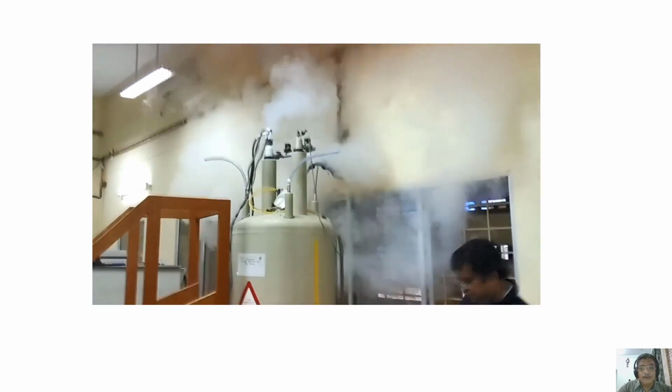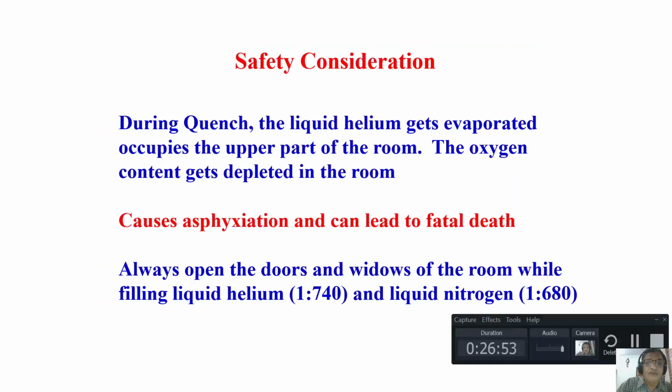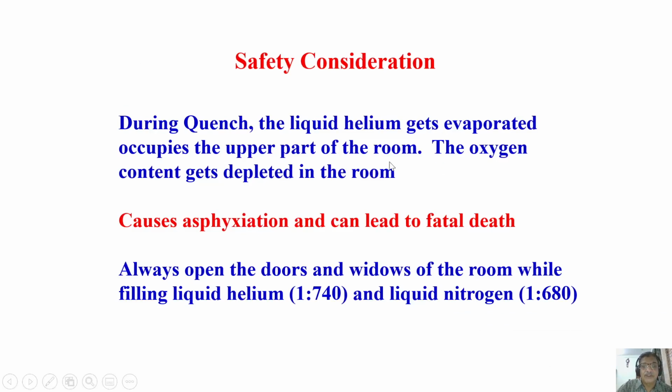Now, with this, we'll go further. Regarding the safety consideration, when the magnet quenches and the helium gets evaporated, as I said, oxygen may get depleted in the room. It may cause asphyxiation and can even lead to fatal death. Always open the doors and windows of the room while filling liquid helium and liquid nitrogen. Do not try to do the experiment by closing the doors and windows while filling the helium. If by bad luck there is a quench, it can be very dangerous. So this is one of the safety warnings I am giving you.